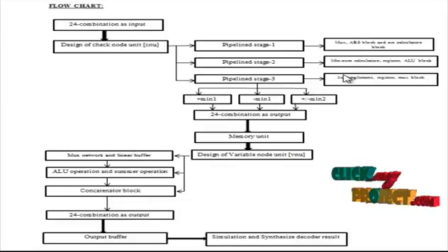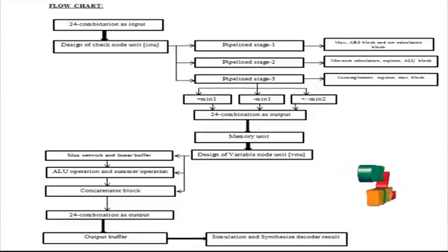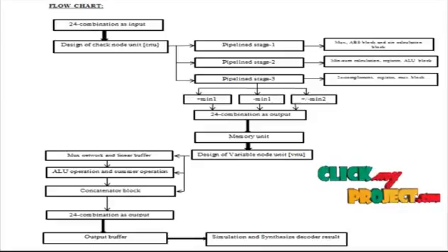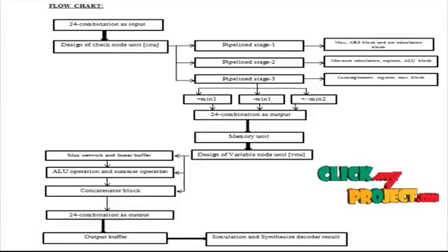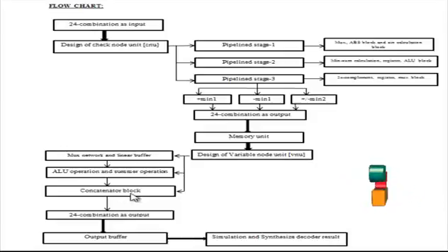So the min-sum algorithm is achieved by using this CNU check node unit, and following the CNU, the variable node unit is used. VNU means variable node unit. The VNU block consists of MUX network, linear buffer, summer, adder and consolidated networks. The output of the CNU is divided into 4 combinations and given to the VNU block. Then the VNU block provides 2 outputs, one gives 5 bit outputs and the other gives 24 bit outputs. The VNU and the CNU blocks play the major role in high performance in the LDPC decoder.